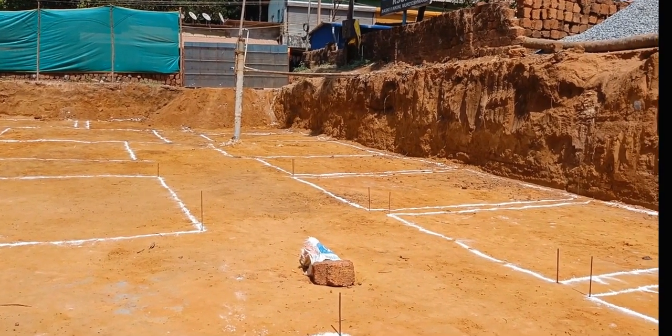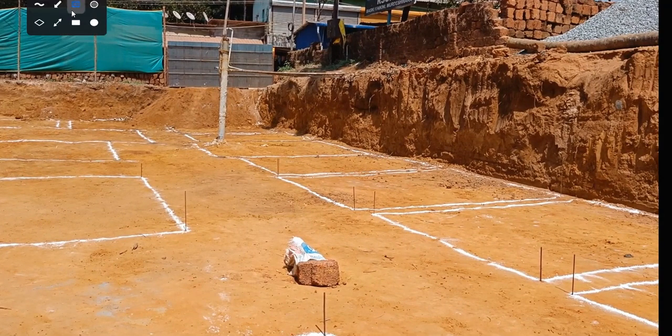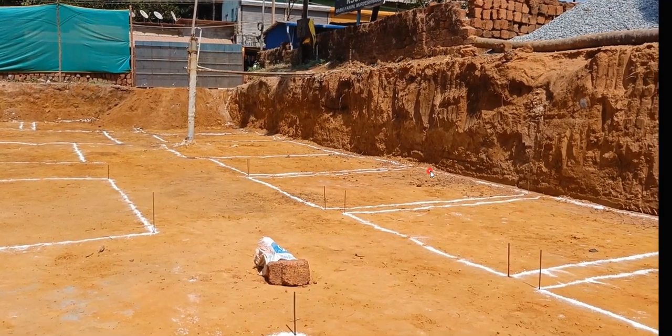Now what the total station guy will do is come and directly give you points. You can see the rod pegged here. He'll give you this outer point, this outer point, and this outer point. Now our task as a site engineer becomes very easy. We just need to connect these points in this way, this way, this way, and this way, and the size of your footing is ready. You don't have to worry about the center point, offset on the left, offset on the right, and all that. He is going to give you the end points directly. Just in case a surveyor is there, this is how the work will be done.